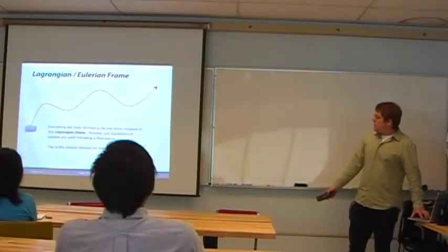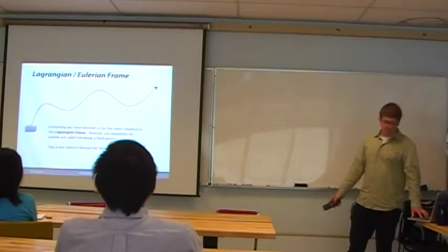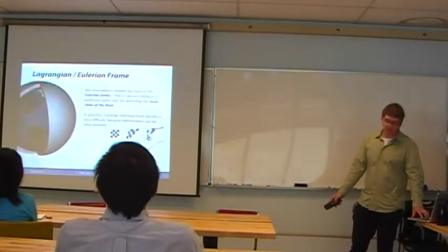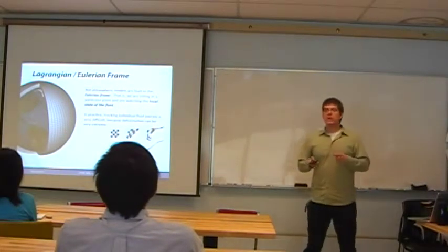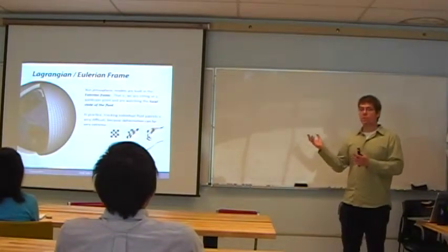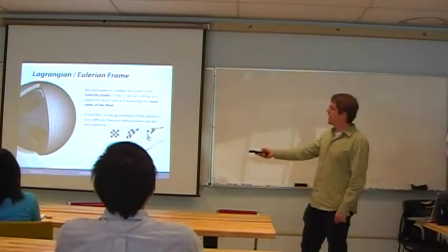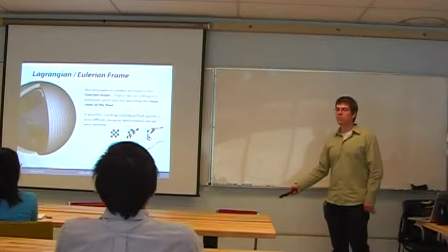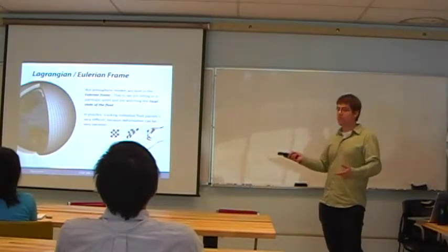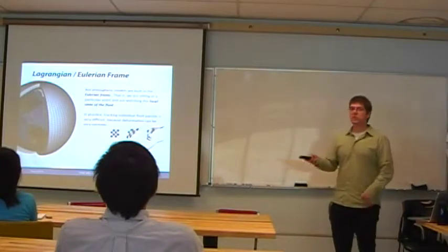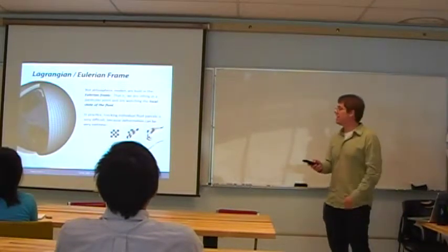So I talked briefly about how we relate the Lagrangian and the Eulerian frames, going back to the notion that in a typical global atmospheric model, we're not going to be dealing with fluid parcels that float around arbitrarily in space, but instead with state variables which are located at explicit points along the globe. This is what is known as the Eulerian frame, since it's a non-moving frame, whereas the Lagrangian frame is associated with actual motion of the individual fluid parcels and their associated deformation.